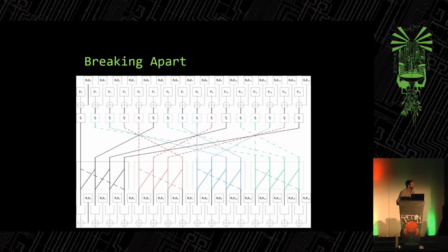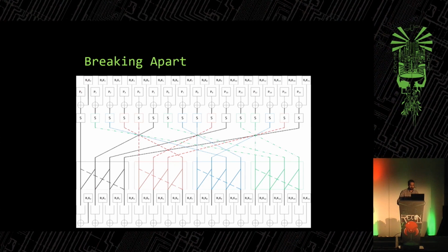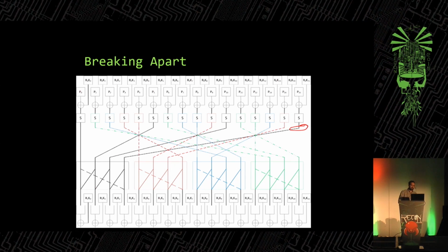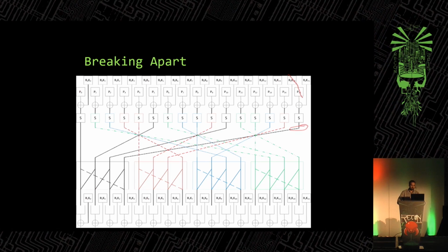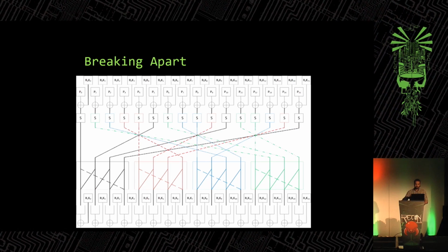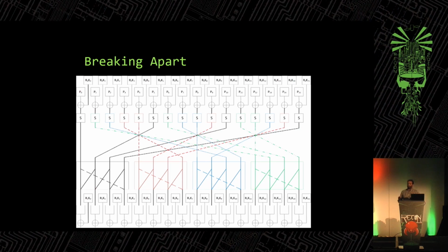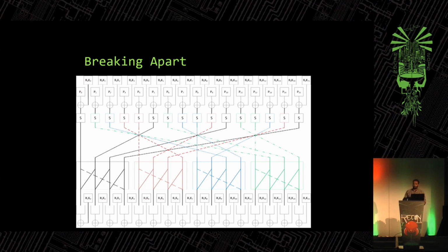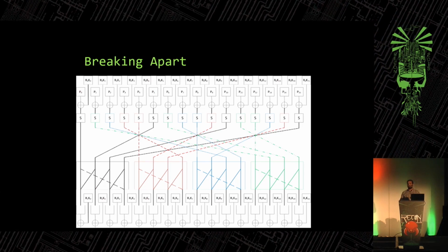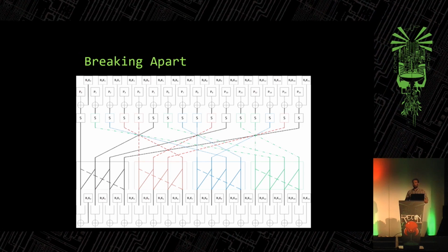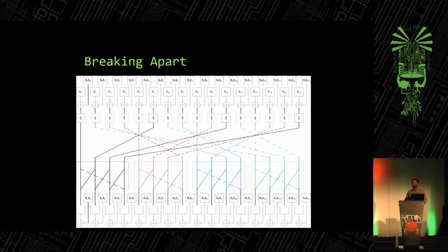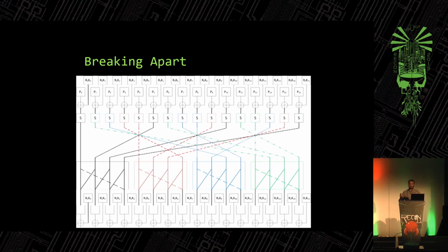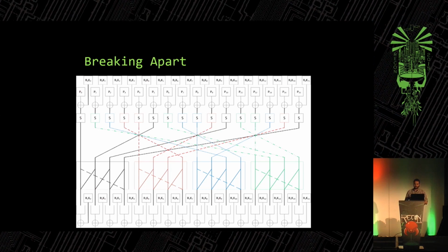So if you can, oh, I don't think it's drawing, sorry. There we go, this output there. So we're only looking at 1 byte of the key, and the output at that one spot. And we could figure out, based on the power analysis, that there were 4 bits set when I put in a plaintext of hex AB. And the only way we get 4 bits set is if the key is some other byte. In reality, we'll of course get a candidate number of possible bytes for that key.